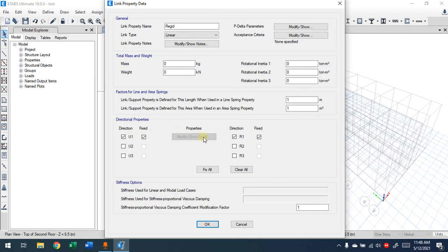For the case I want here, I want everything from the column and the beams to transfer to the column. So I'll fix all. That's what we call rigid. So you have semi-rigid, you have rigid, you have just one direction: X direction, Y direction, Z directions, that you can allow the loads to transfer from one joint to another joint.